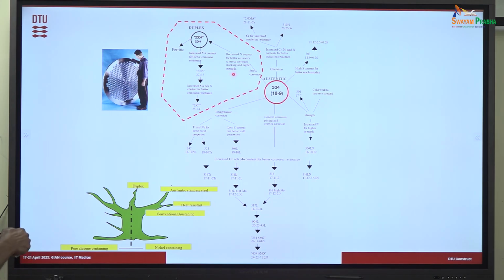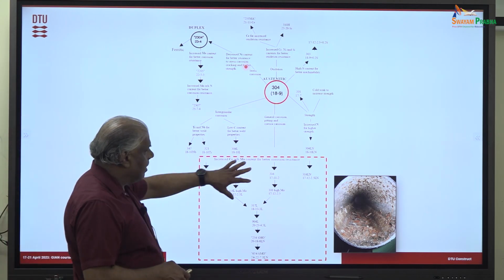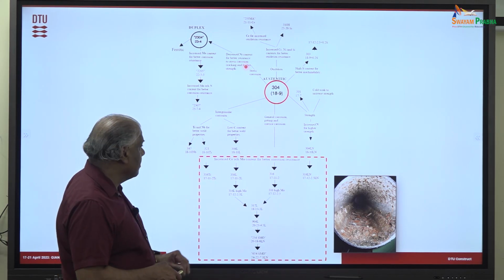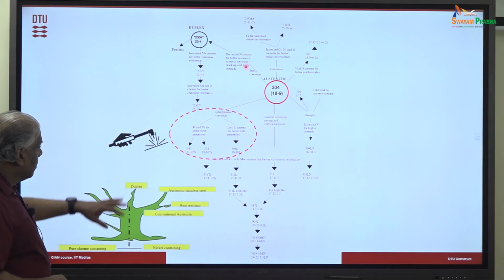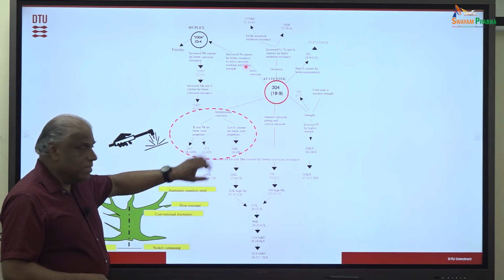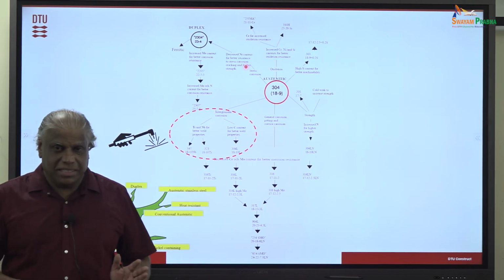And here it is written that decreased nickel content gives better resistance to stress corrosion cracking and higher strength level. If you look at another area here, you can see that with chromium and higher molybdenum content, there are many steels again developed for higher corrosion resistance. Corrosion-resistant stainless steel is built only for the welding purpose, because when you have welding, what's the biggest problem with stainless steel when you do the welding?